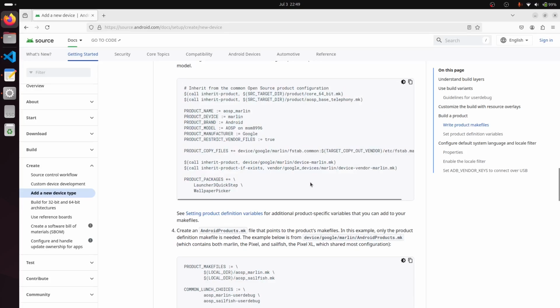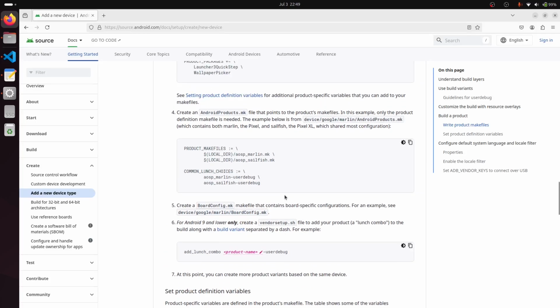The third is the board configuration. If you're running your own board, the custom vendor will supply the boards, so you have your supplier configuration which you want to include to bring up your board and do the necessary work. You need to configure all those things in the boardconfig.mk file.